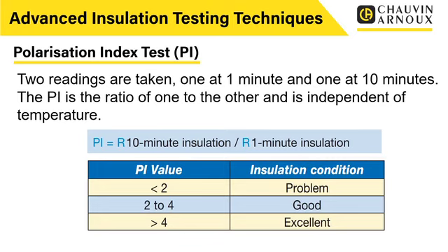And this gives us excellent time for that insulation polarization to take place, and for us to get a key idea of what's going on. Sometimes, for higher test voltages or for bigger installations, this may be a good idea to try. Again, you can do both. You could try a DAR test, and if you're not 100% convinced with that, go for a polarization index test. These aren't exclusive. You don't have to just pick one. You can carry out these tests and see the difference.